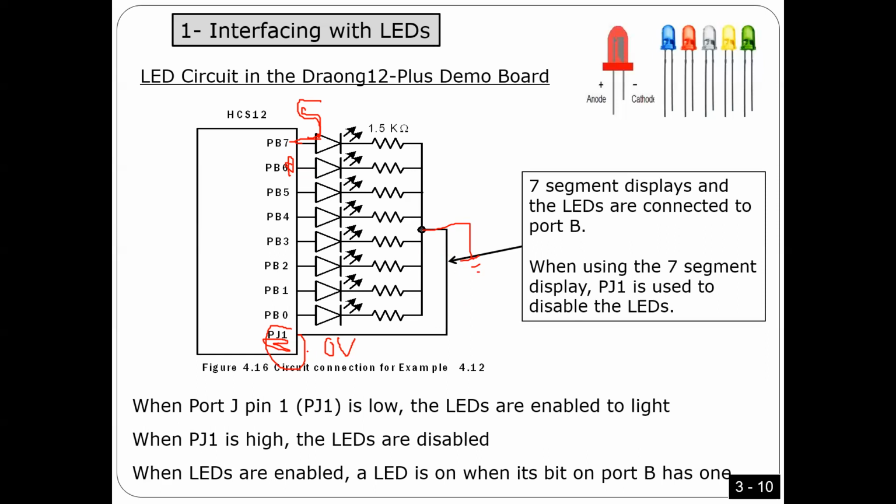What do you mean by disable? It means it's not working. So I don't want the LEDs to work. Okay. So very simple. In BG1, I can put here 5 volts. So in this bit, I can put 1. When you put 1 on this bit, I'm going to put here 5 volts. Think about it. If you have 5 volts here and you put here 5 volts, the LED is off. You have 5 volts here and put here 0 volts, the LED is off as well. You got what I'm saying? That is why BG1 is used to enable or disable LEDs.